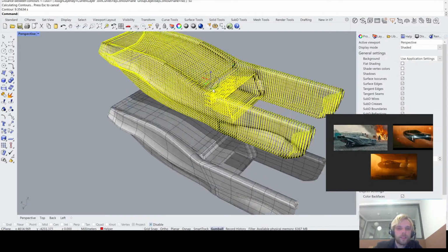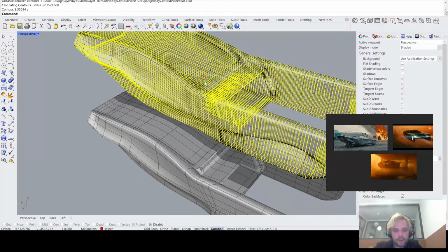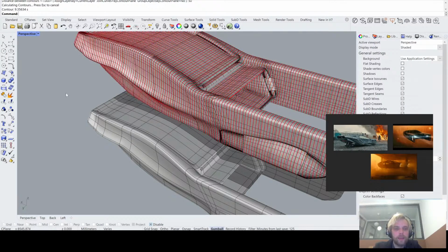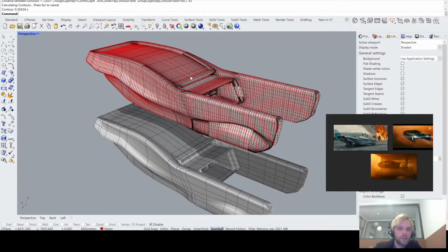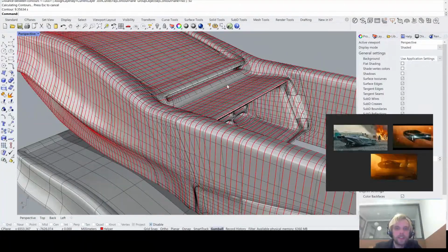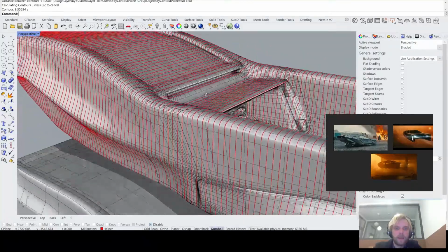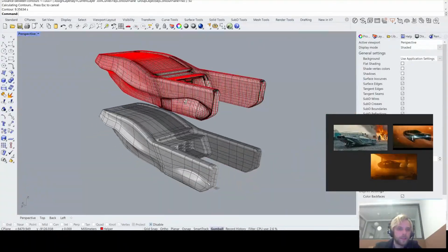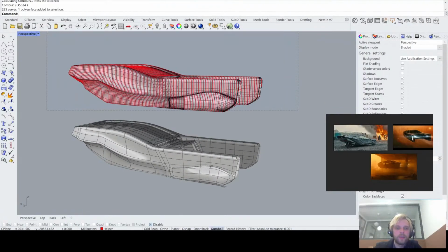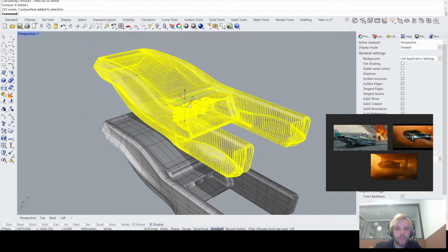So getting a bunch of contours, and just to be safe, I will move them by 1 millimeter to the side and up. You could also offset the contours just a little bit. But basically you end up with this view, right? And then you select the whole car thingy together with the contours, and you do Make2D again, and technically it should be a better output.